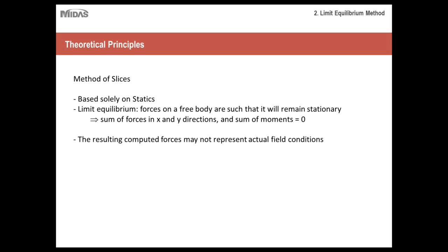That's another important thing to keep in mind. If, for example, you check the forces acting on those slices, just keep in mind that there are various assumptions made when doing the limit equilibrium method, which can lead to forces that may seem erroneously high or erroneously low. Those don't actually represent actual forces in the field.